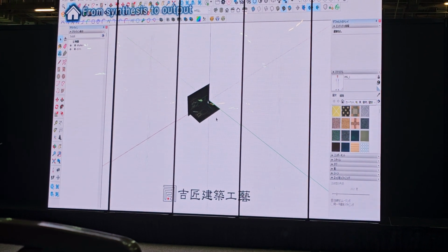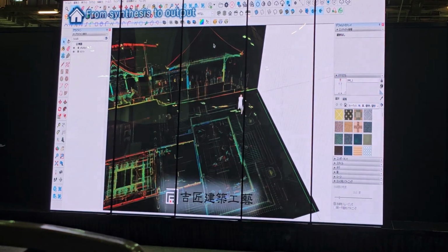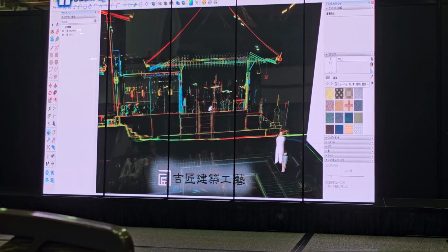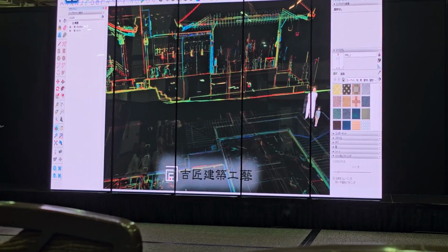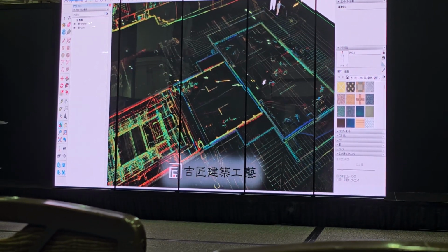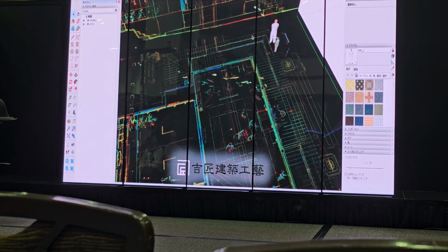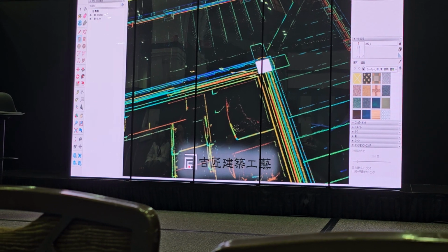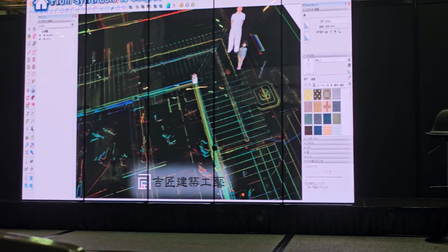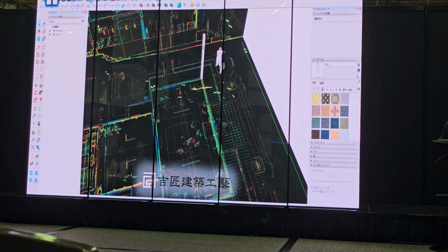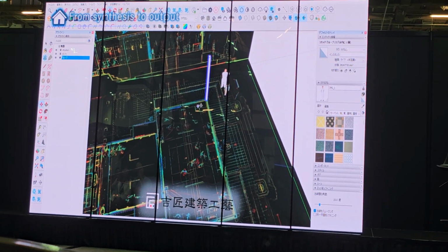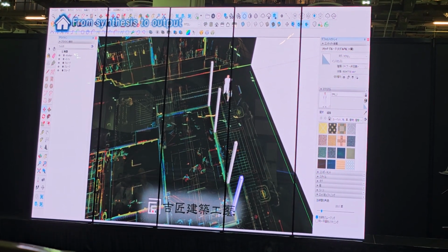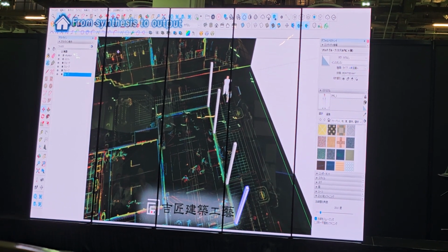I won't spend too much time on this, but basically he's using Trimble RealWorks, importing a point cloud into Trimble RealWorks, doing a slice, right? And there's a send to SketchUp button from RealWorks. So this is after he imports the sectional view into SketchUp, and then he just relies on this and starts sketching the columns in SketchUp. The push-pull is just drawing, extruding, and then making copies of this. And this is really the foundation of how people start modeling with SketchUp. It's very easy, right? It's direct modeling. There's no parametric relationship between the first beam and the second beam and the third beam, right?